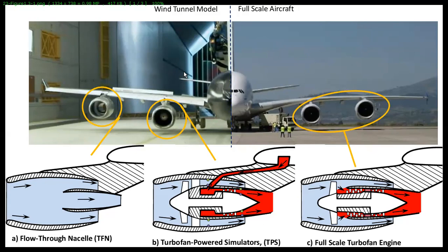But there are problems with sensors, and in case of low angle of attack, the system thinks the angle of attack is very big and puts the nose down, and the pilot doesn't understand what's going on, and two airplanes crashed. And this chain of accidents started from an increment of engine thrust. So proper simulation of the engine is very important for aircraft design.